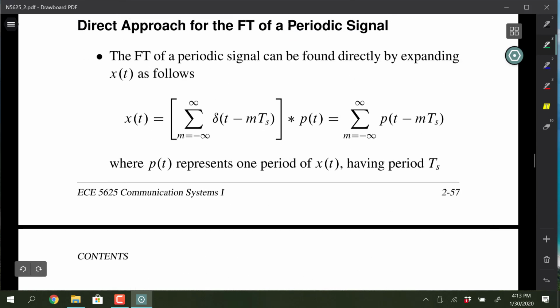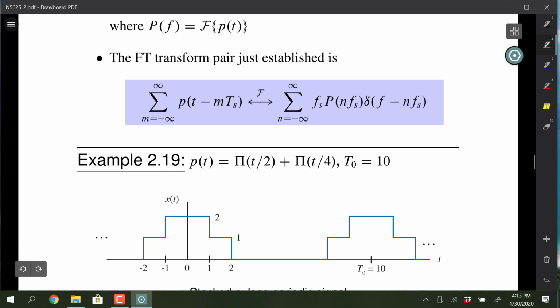Let's see, this theorem right here shows up in Lab 2 a lot. It says if we can look at one pulse associated with a periodic signal, and we assume that a superposition of time-shifted pulses, on the left side here, forms our periodic signal, then we can get a spectrum of that signal in the Fourier context. All spectra look like they're in Fourier transforms, except now the line spectra we've been talking about get represented using delta functions to place the spectral lines.